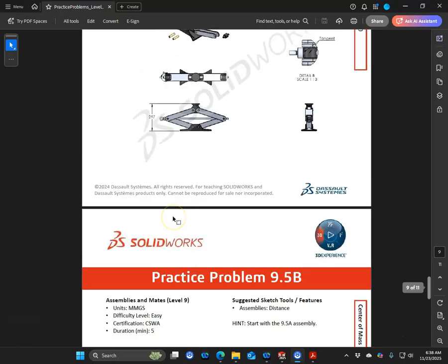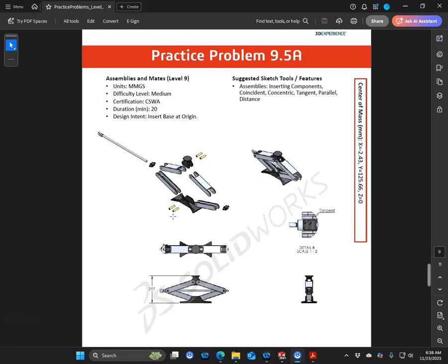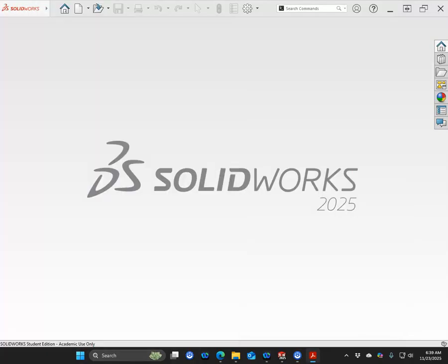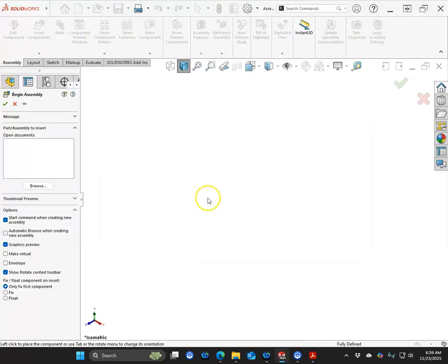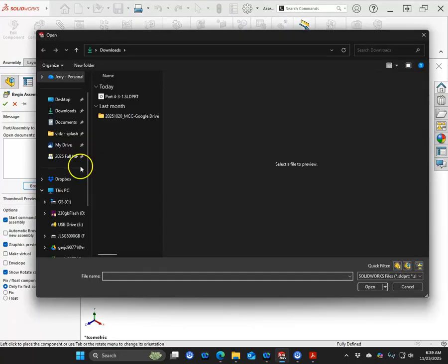So for our purposes, my assignment, I'm also going to do the exploded view and the drawings. So we want to go through the process from taking the parts into the assembly and all the way through creating the working document. All right, so insert the base at the origin. On the previous videos, I've been saying click the check mark so that it goes from part origin to assembly origin. So we'll browse over to